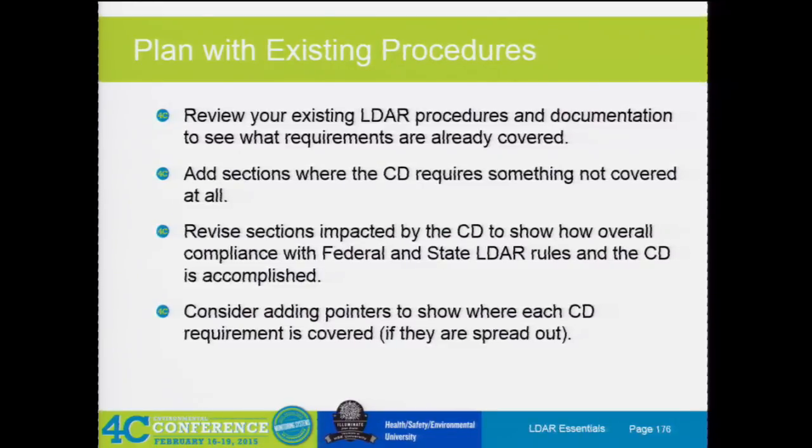So with this, in the consent decrees, you're going to have minimization attempts. Some folks, if it goes over 100 ppm, you have to make an initial attempt at repair. It didn't trigger a leak. It didn't trigger a federal leak. It didn't trigger a consent decree leak, but it triggered a minimization attempt. And so you actually have to have logs, and that's where databases come into play, that a technician actually torqued on the valve, or that you did something to help catch this.